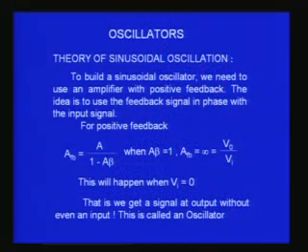Oscillators are very useful for different applications, especially in radio communication and things like that. So let us see how we can build oscillators using an operational amplifier. That is what we are going to discuss this time. In order to build sine wave oscillators, as you can see on the screen, we need to use a well known amplifier. Any amplifier can be converted to become an oscillator, but you have to give it feedback. To become an oscillator, an amplifier should be given feedback.